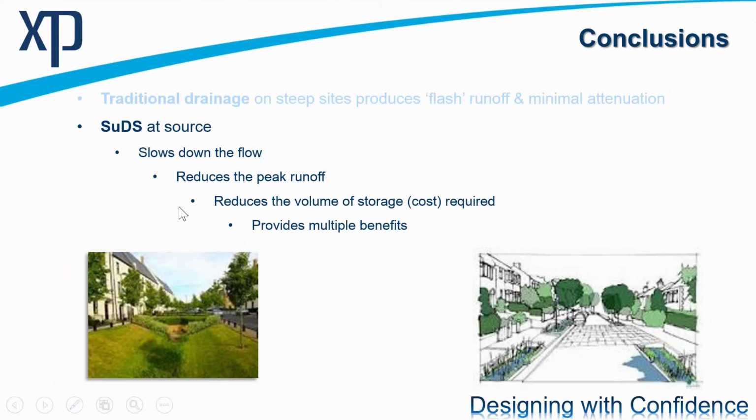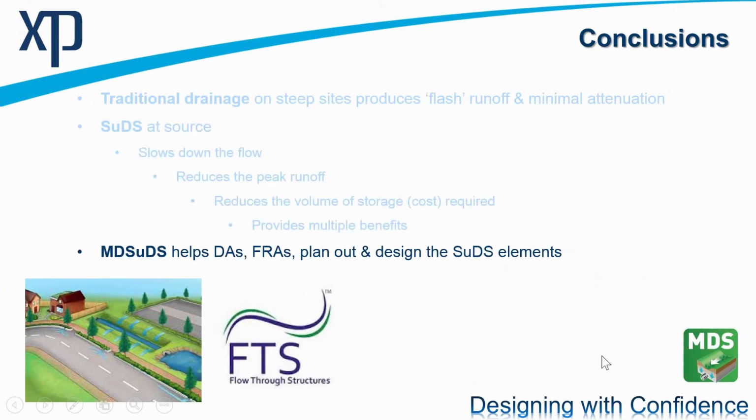So in the screenshot here, for example, coming out of the SuDS manual, they're asking us to retain the water for at least 9 minutes within a swale, 9 to 18 minutes within a pond, adding in those retention times. But apart from the quantity of the water, we're looking at providing multiple benefits by enhancing biodiversity, improving the ecosystems. We're adding in water quality capability as well. And isn't this a nicer place to live?